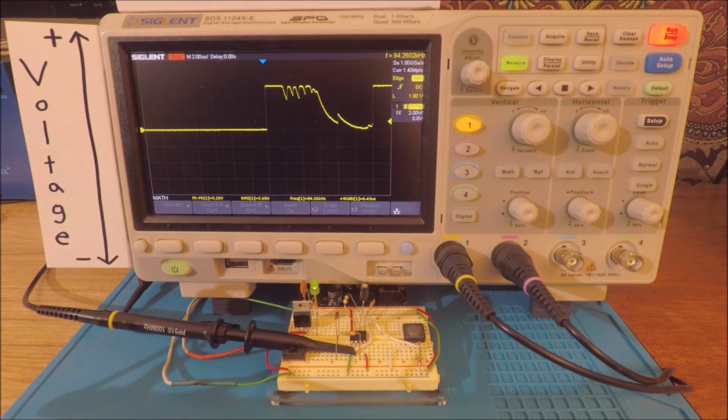This might not matter if you're just turning on and off an analog circuit, but if this switch was the front end of a digital logic circuit downstream from it, we could end up creating some interesting logic states which are going to end up misfiring when the switch bounces in this manner. Therefore, we need a better way to handle an input such as a momentary switch like this if we're going to drive some digital logic.